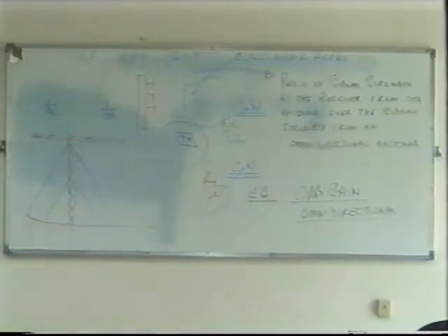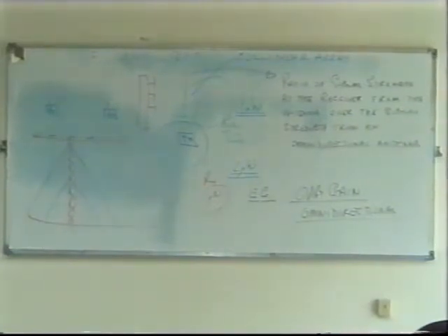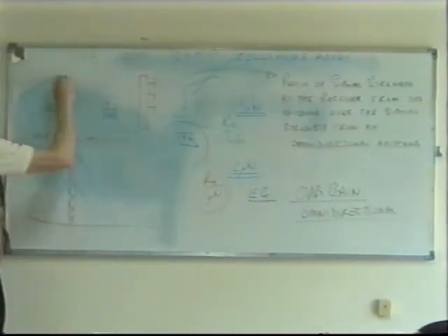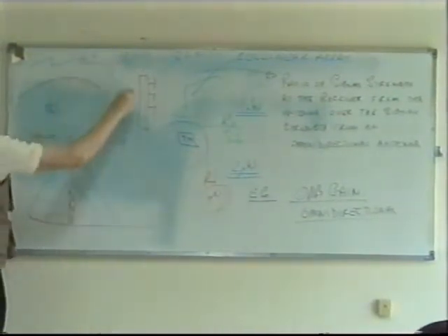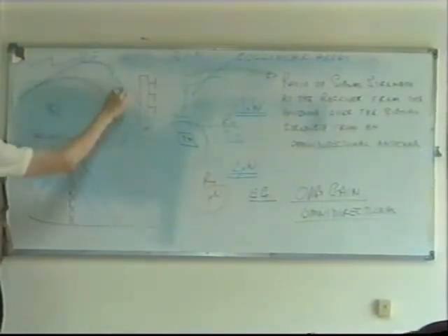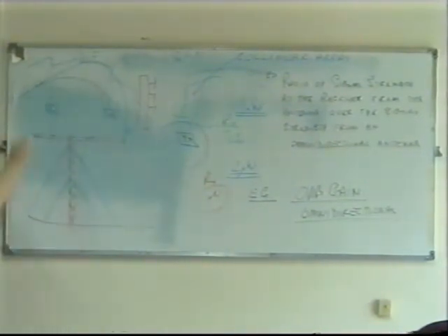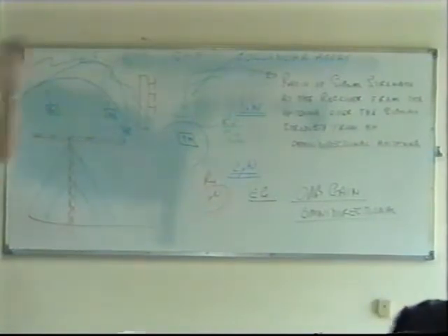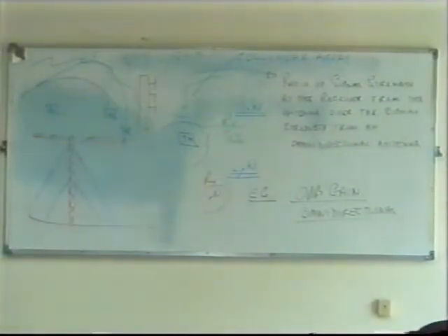This is the log periodic. It is a directional antenna. It's supposed to be omnidirectional because you're using every one of these. Not necessarily. Remember, on HF communication, you use the ionosphere, isn't it? Yeah. And the idea is to get reflection from the ionosphere. But really, you don't want to waste energy in the other direction. You know precisely the location of where you want to communicate to. This could be London or New York or any of the other stations where we could have aircraft. You know roughly the direction, and you don't want to waste energy in the other direction. So a directional antenna will work, even though it's using the ionosphere to do that.